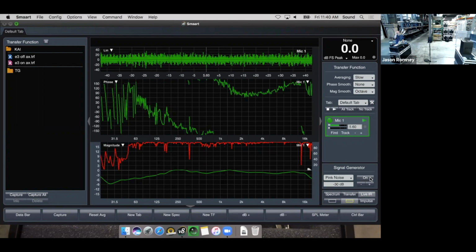Your brain will reject that little laser notch as an error. And so I tend to make at least third octave range adjustments. If the filter range that I'm adjusting is not at least a third of an octave, then there's not a whole lot of point in trying to do that, because that's not breaking through the critical band blind spot of your hearing system.